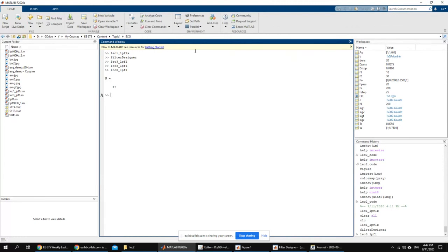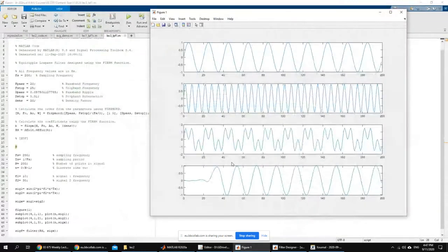And the longer the filter, the higher the order of the filter. This is the order of the filter. You will see that in the output, the transient becomes a little bit longer. You will find out maybe by the end of this lecture or probably next lecture that this transient actually is equal to n over 2.